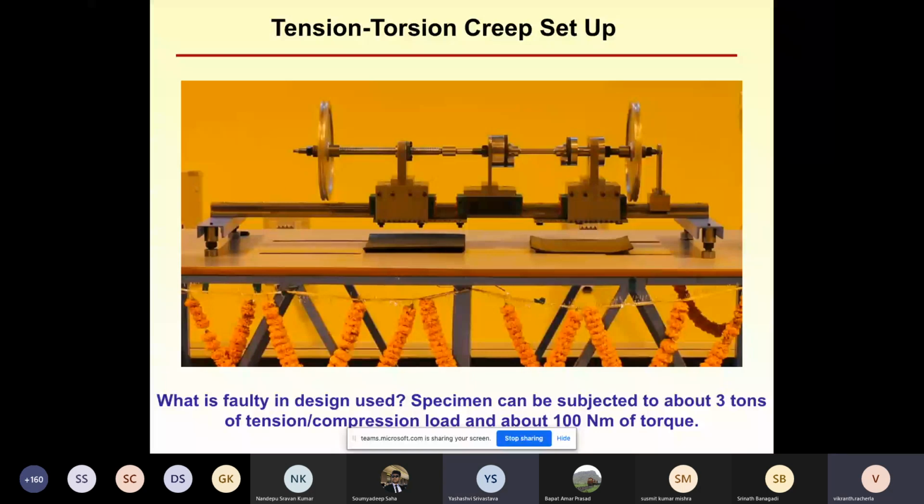Okay, so I thought you got the answer, but that's not the answer. Mainly due to the moment, due to the dead weight, it is causing the tension. Again, dead weight is very little. These things are not that heavy that they are causing any huge deformation anywhere. Maybe a part of tension and torsion that we are applying through this whole process gets transmitted to this rail due to the clamps that we have created. Again, tension will not do any harm. Torsion does get transmitted, but torsion was not the problem.